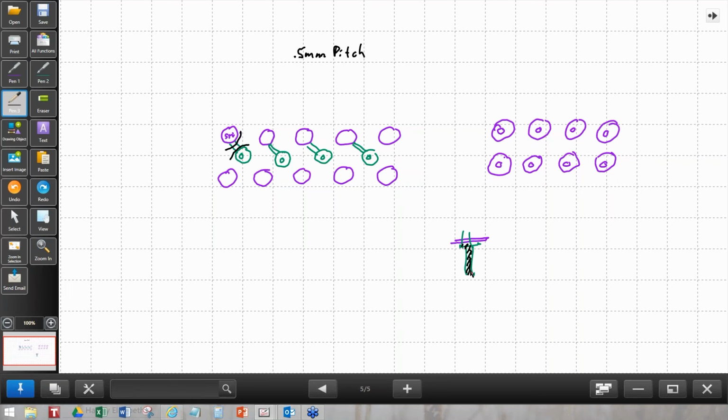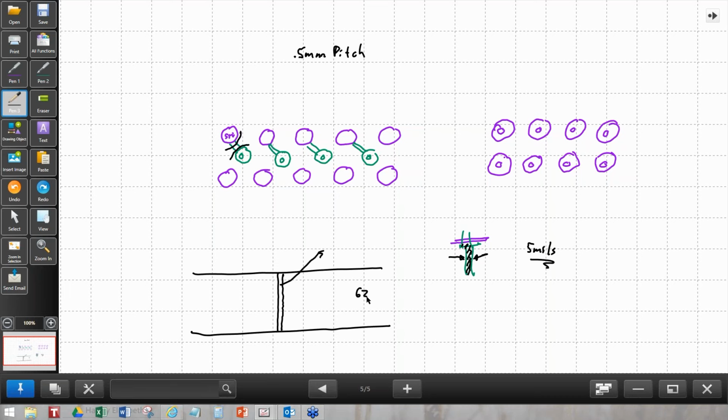Usually the diameter of these holes gets fairly low. It can be a few mils, like 5 mils in some cases, which is pretty small. And so how do you plug that? Well, on the surface of a board, they might come along and say, okay, here's the via that you need. First, in order for this to be 5 mils, if this is 62, it's going to have a very long L/D ratio, which makes it, number one, hard to manufacture. Maybe it'd be manufactured with micro vias. You'd say that'd be great. But micro vias are hard to plug.